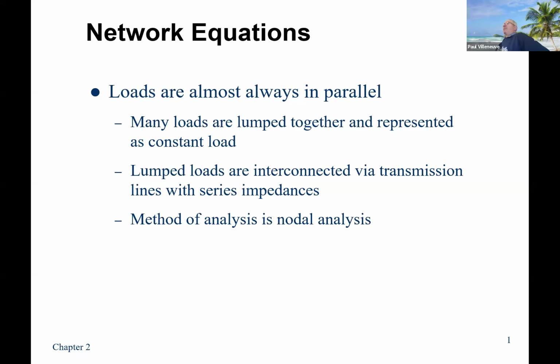But the reason why we have to spend a little bit of time understanding how to build what we call Y-bus is because in a real world power system, you might have millions and millions of nodes that you're needing to calculate voltages for. And if you remember from your circuit analysis days, when you calculated node voltages, you had to write an equation for every node. And if you have a million nodes, you have to basically write a million equations, right? Or a million equations minus 1.